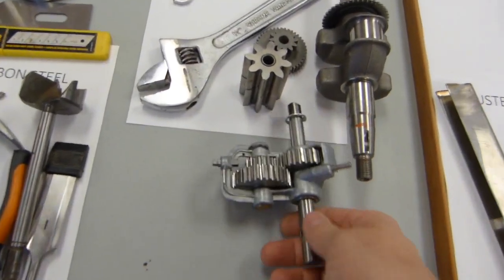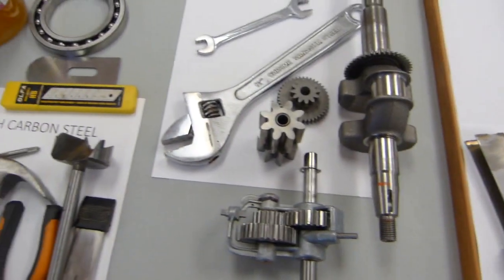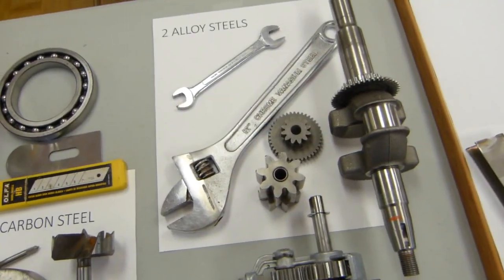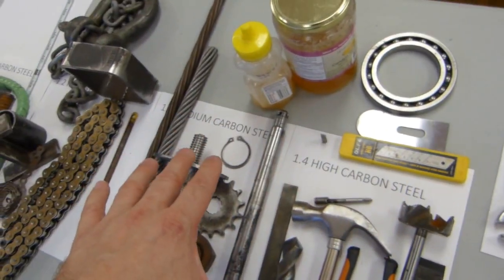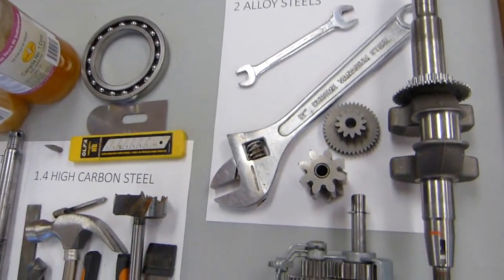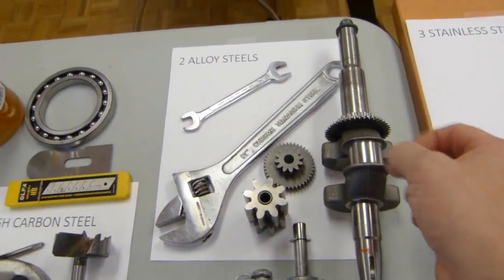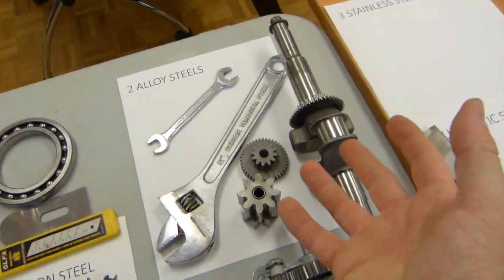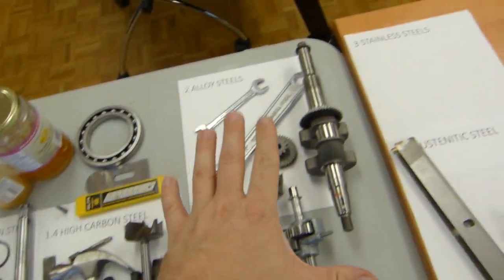I have here other smaller gears here. Okay, none of this stuff. If the gear teeth break off, good luck welding it back. It's not really going to be successful, much for the same reasons as they are either based out of high carbon steels, or they are based out of medium carbon steels typically, and on top of it, like I said, they have this sandwiched structure to it, a harder case hardened, and a softer inside. So as soon as the welding torch touches it, it's gonna change the hardening, this layering in it. It's not going to work. All right, end of that story. So they are not hardened, or not really weldable.